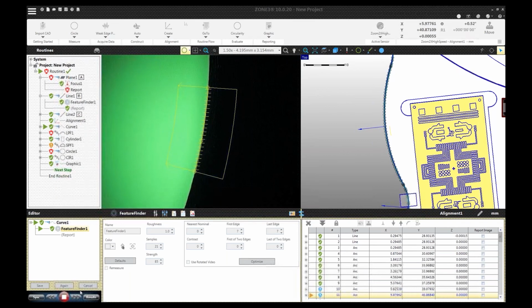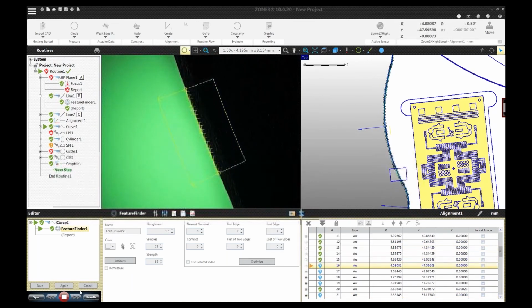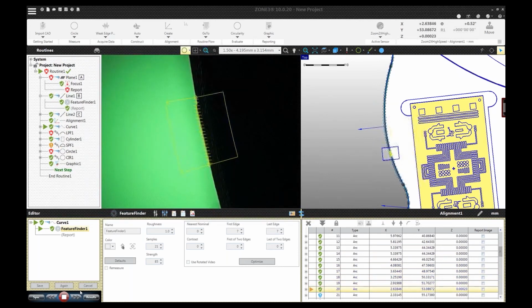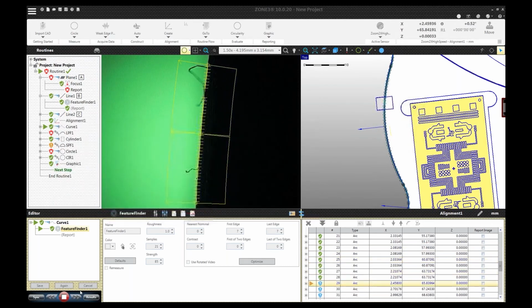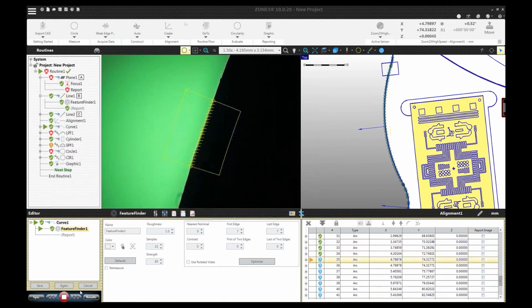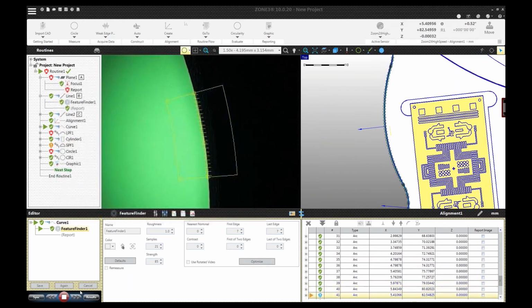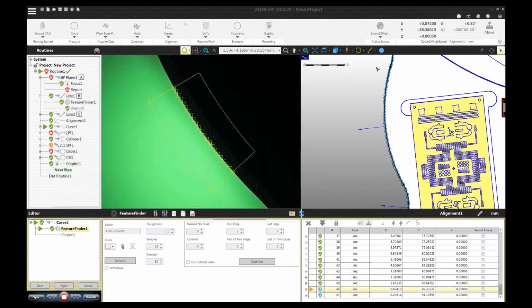But again, with the graphics, you're able to not only get a number, because the profile measurement is a deviation, it's a worst case scenario or a worst point type of measurement, but it's nice graphically to be able to look and see where it is. If this is for manufacturing feedback, I'm sure your machinists are going to be very happy to actually see, oh, I've got excess material here, or I've got this bulge here, okay? That kind of thing.